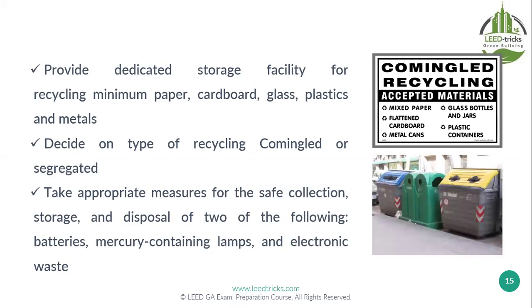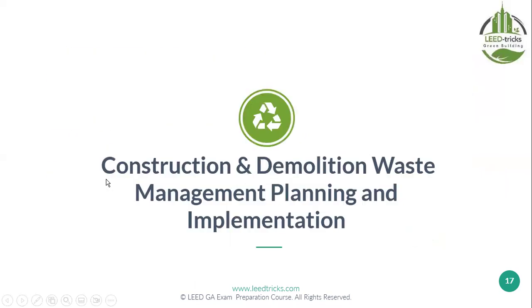One thing here: the waste area is from LEED AP, but you need to know, because sometimes it comes up in the LEED GA exam, the waste area should be accessible with clear signage and easy access for the waste truck. And it should be in a safe area, contained in one area specific for waste, and everyone knows this is the waste area, with access for the truck or for the people who use it.